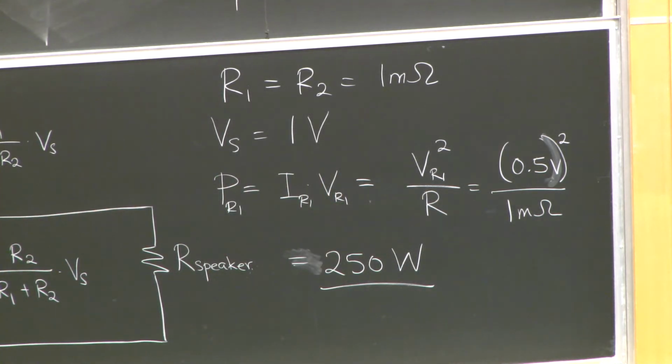That is a lot of power, really a lot, okay? The resistors in the lab kit that we give you are rated for 1/4 of 1 watt, meaning if you put more than 1/4 of 1 watt through it, it will explode. Like you'll see it get charred. Okay, it won't explode, but it'll melt. Please don't do that.